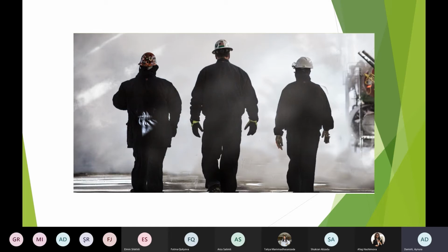My focus area is that on site there are different types of equipment which need to be monitored, and not always do inspection techniques need to be applied. It could be just a visual check, where you go to the site and say, okay, equipment is good for operating, nothing is happening, and that's it. From an integrity point of view, equipment is fit for service.